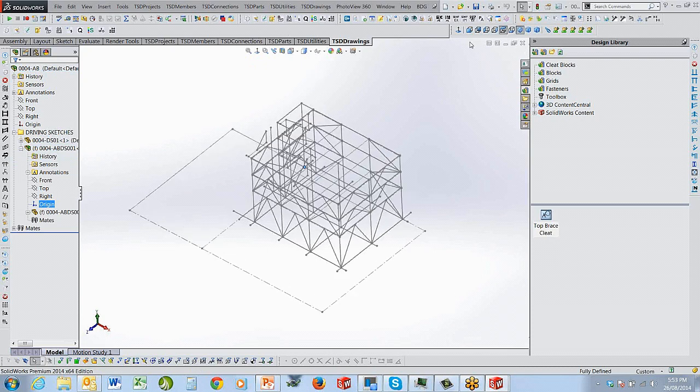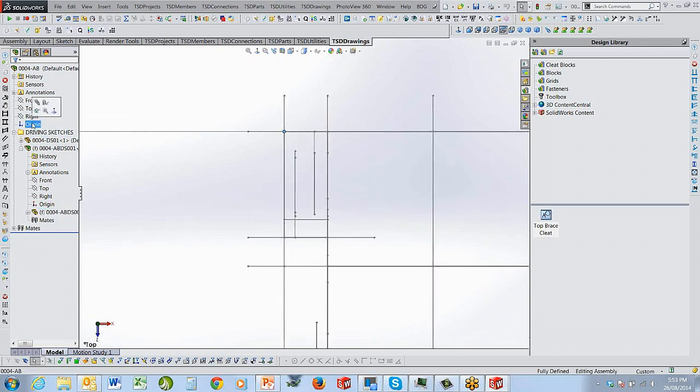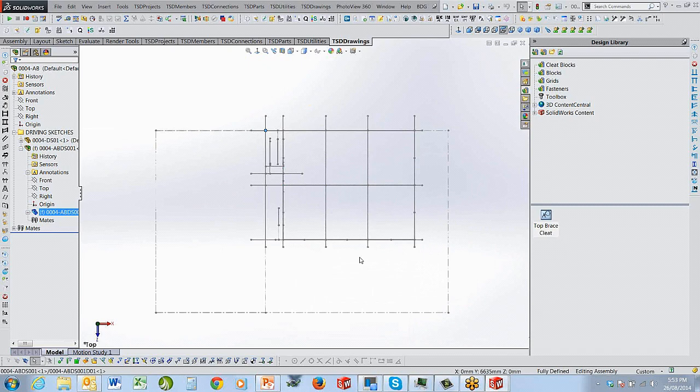You do not want to have your main driving sketch sitting at origin, because if someone changes the position of your main driving sketch, all your drawings are going to go out of whack at this level. You don't want that to happen. So basically what we've done is we overlap or overlay the DS01 so that the position to which it's attached to, in this case is right there, because that's where the origin is where it would be related to in the top level assembly.